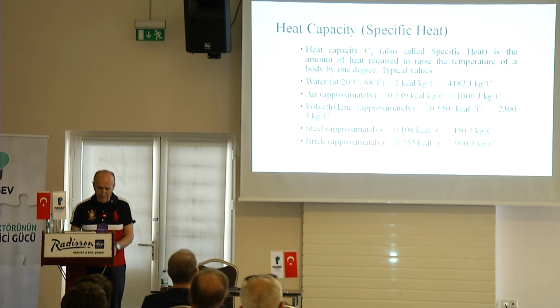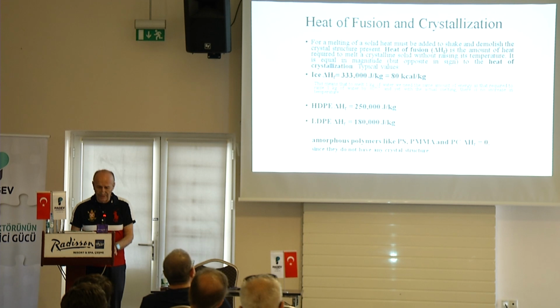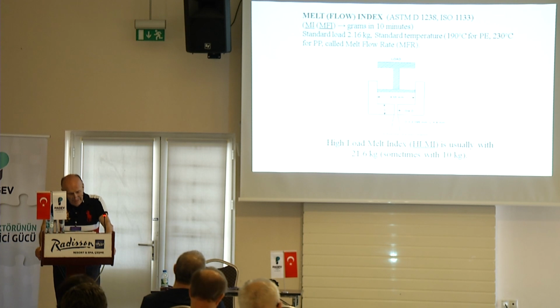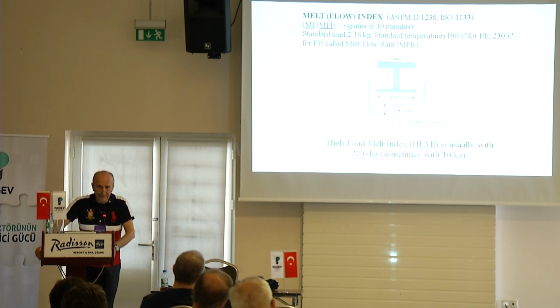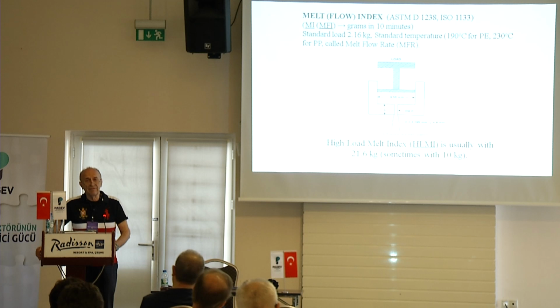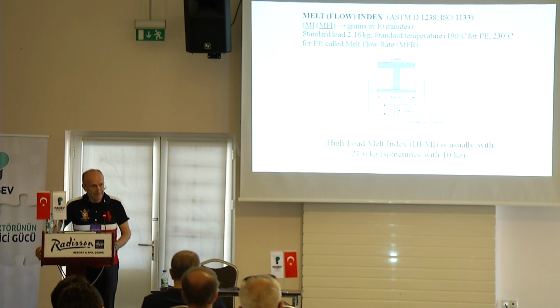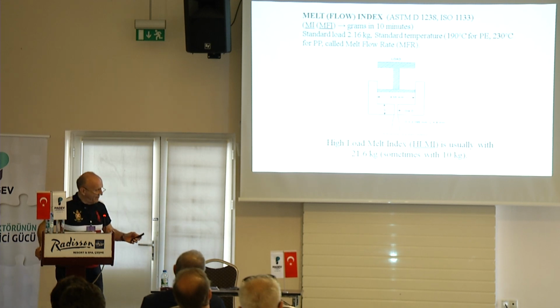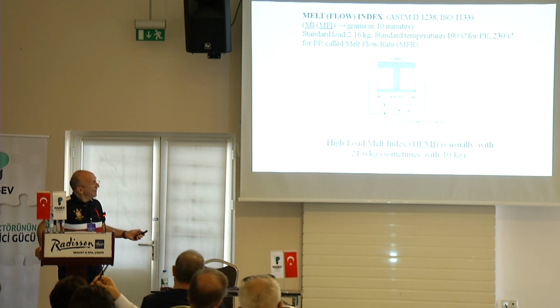Heat capacity, also of importance, heat of fusion, crystallization, and melt flow index. Now, melt flow index is a very, very simple rheological test. We have a certain weight pushing against the polymer, and it is forced through a very small die.